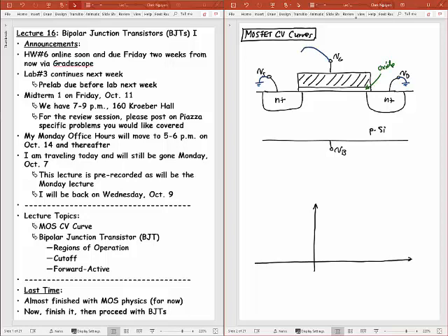So here I'm just going to want to apply plus minus some VG voltage to that. And so as I'm doing that, you know what occurs in this. So the first thing that occurs when VGS is very small, and this is in the cutoff region, say when VGS is 0, so I can come down here and say at 0, what is this going to look like? It's going to look like something where I have a depletion region, as we talked about. So I'm going to have a depletion region around my source and drain, but I'm also going to have a depletion region